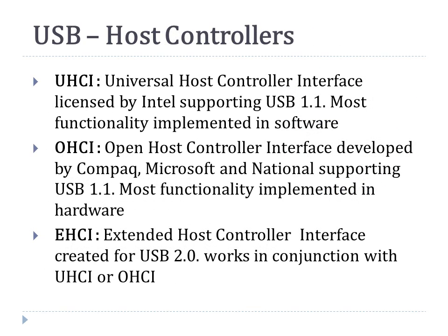So across the various generations of USB, there were several different controllers that have been standardized. The first one is UHCI, the Universal Host Controller Interface, which was licensed by Intel, and implements most of the functionality in software. And OHCI is also for USB 1.1, developed by Compaq, Microsoft, and National, and most of the functionality is implemented in hardware. With the evolution of USB 2.0, the EHCI, the Extended Host Controller Interface, was created, and this supports the USB 2.0 functionality, and this works in conjunction with UHCI or OHCI.